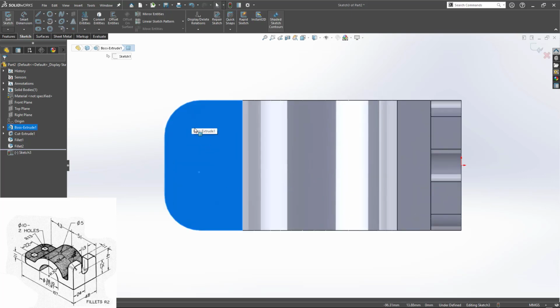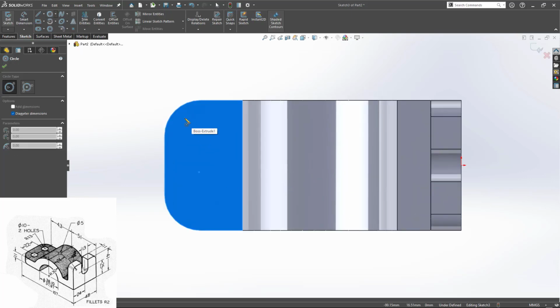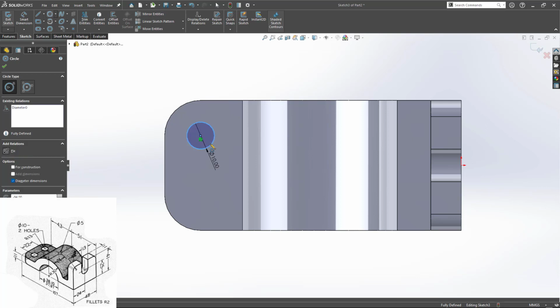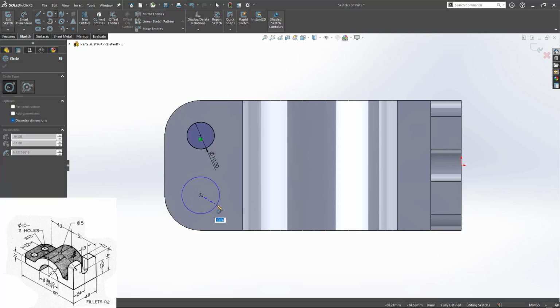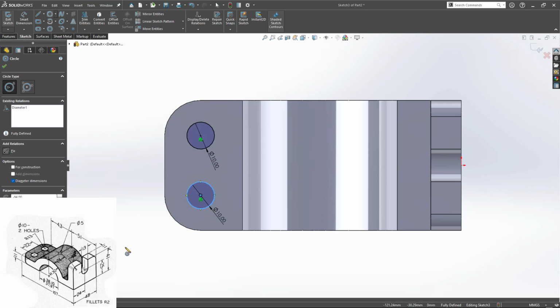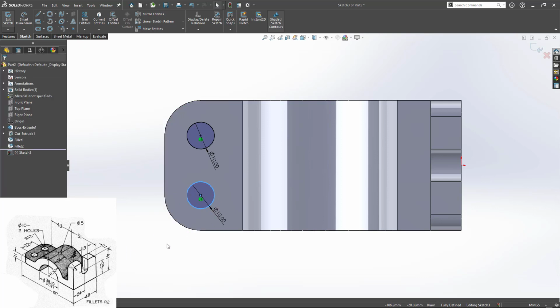Now we can refer this C for circle. If you just hover on this, it will give the center, and on the center the value is diameter 10. Similarly here can have this. It is done. Yeah. This is one method, or else you can just simply draw somewhere and you can use other tools to define the dimensions, but I would like to have this.